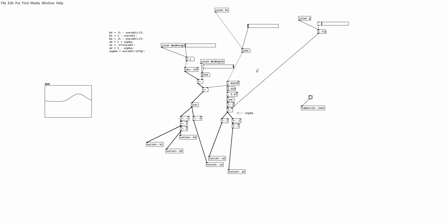So here we're just going to talk very briefly about how to generate filter coefficients using PureData. Now, there are obviously infinitely many reasons why we might want to do this, but to specifically address why we might want to use something other than the blocks that are already provided by PureData, for example, the VCF object is relatively limited. I believe it provides a fixed first order low pass filter, and it does allow you to modulate the cutoff frequency as a function of time, but it does not allow you to modulate the Q of that filter as a function of time.